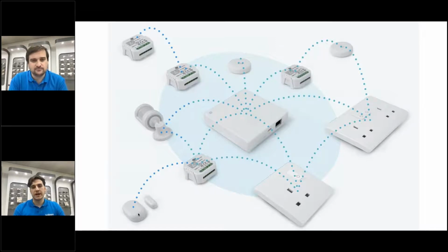The reason for that is because they are battery operated and they cannot repeat the signals via battery operation. Some manufacturers may do it, however, we've chosen not to do so because if it does start to repeat a signal, it does have an effect on the battery life. Yes. If it's affecting the battery life, chances are that it's going to affect your system further down the line.